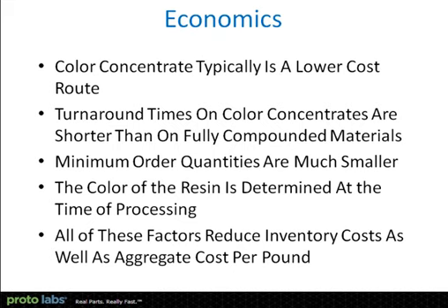And this is a common problem, and a lot of this relates not so much to the color concentrates themselves, but to the equipment that is running in our machines. If you talk to people who do extrusion, they'll look at your injection screws and kind of just shake their heads and say, well, it's no wonder you're having mixing problems. General purpose screws don't really do a very good job of mixing. And there's a lot of good technology out there to enhance mixing if you're willing to go out and experiment with what we call mixing screws. And very often, if you're going to color, especially high viscosity materials like polycarbonate, you're going to need to get into those kinds of technologies in order to be successful.